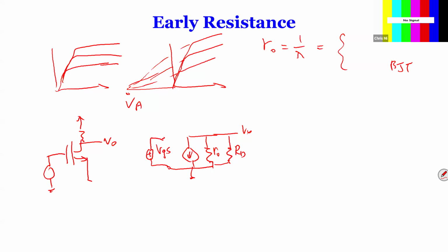The reason is, if you remember, in the DC operation we had a resistor RO like this, and we put it here. So that's how we got this equivalent circuit. If we replace this middle one with a small signal equivalent circuit, which is this part, and simply add RO, you get the actual equivalent circuit.